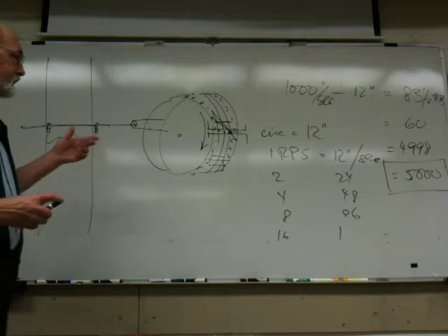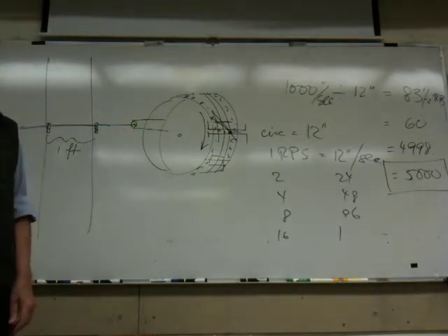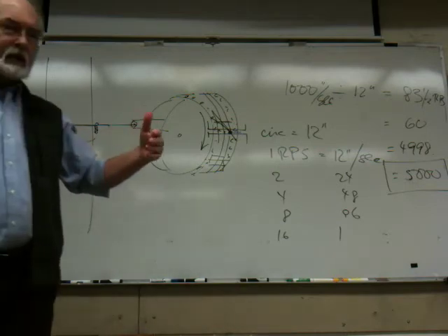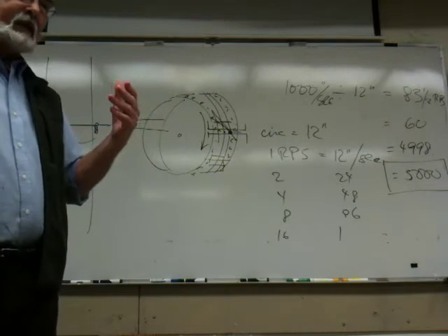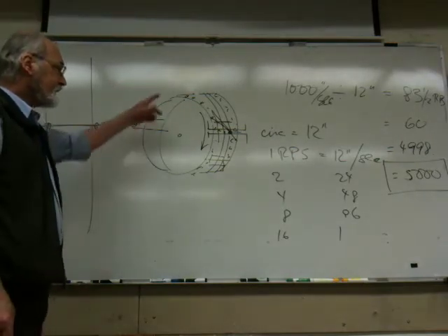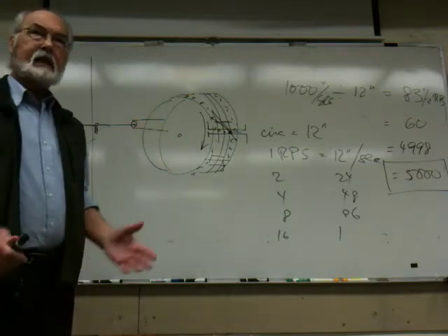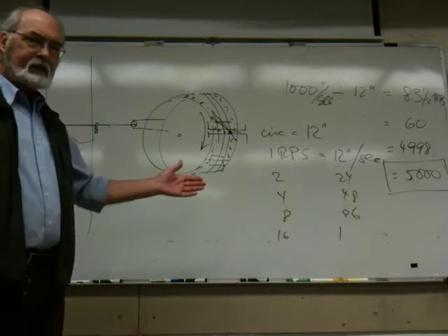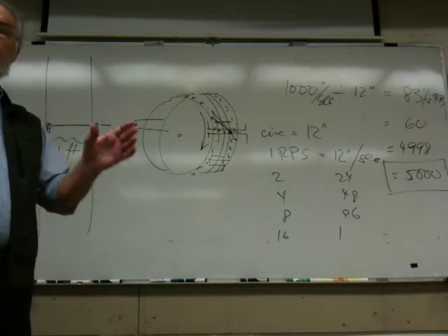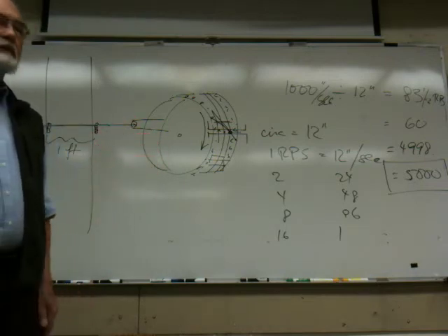Now because a drum camera like this, and we'll run it across another one next week, because it is a drum camera, it has some very useful characteristics. One of them is that the speed at which this recording medium is moving is constant, so that you can tell that any place along the length of the record, a certain distance along the film stood for a certain amount of time. In some other camera systems, that's not the case.